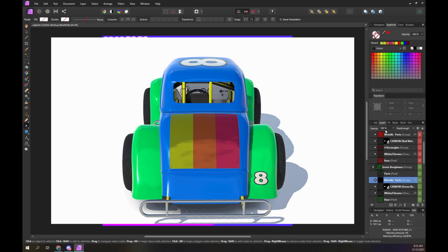In addition to adjusting the base paint color, you can experiment with the spec map values. More red for more shine, more reflectivity, more metallic effect. For a metallic effect we typically use very low roughness values. Some roughness can be a good thing. Brushed aluminium and satin effects for example.